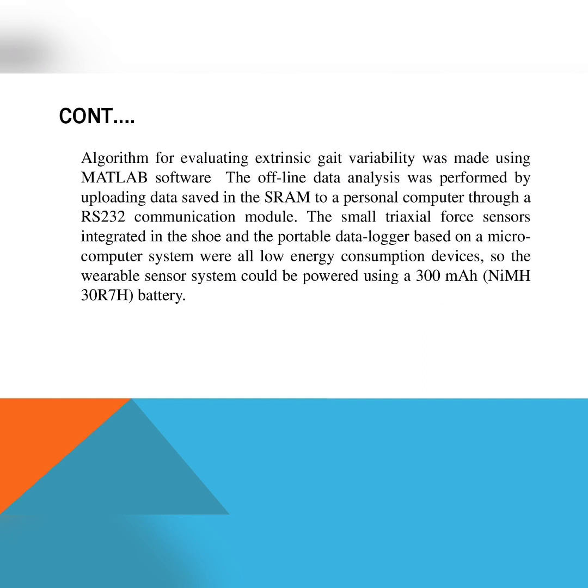The offline data analysis was performed by uploading data saved in the SRAM to a personal computer through a RS-232 communication module. The small triaxial force sensor integrated in the shoe and the portable data logger based on a microcomputer system were all low energy consumption devices. So the wearable sensor system could be powered using a 300 milliampere hour battery.